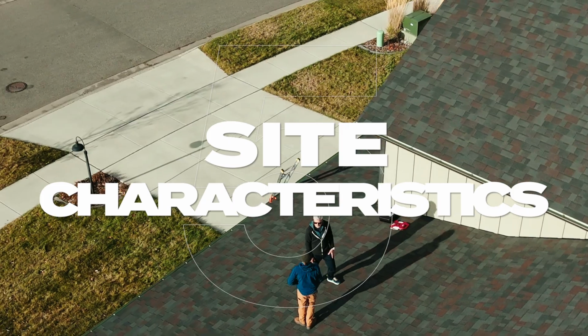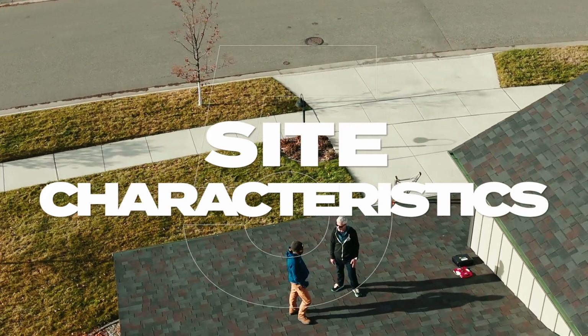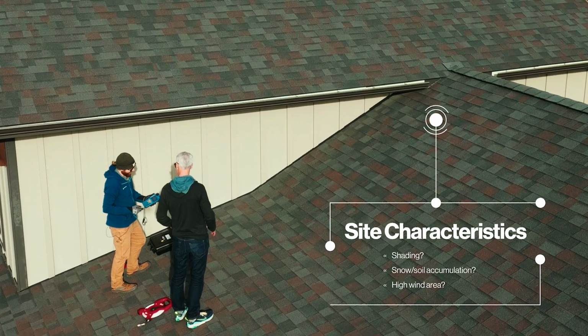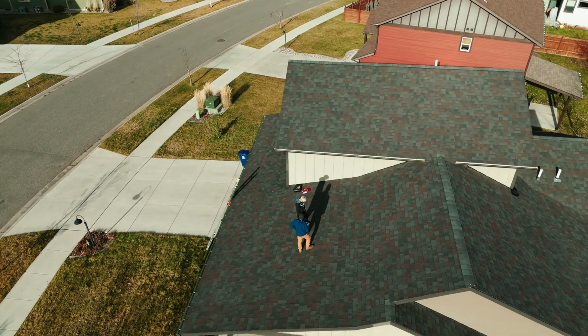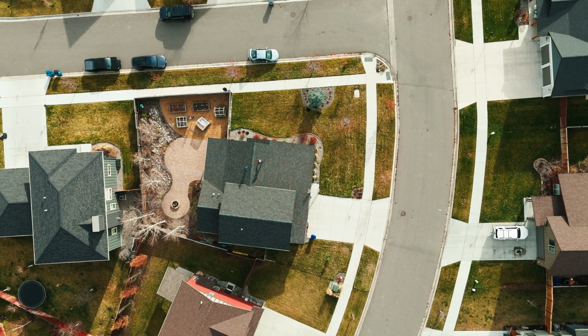Site characteristics are the final step in assessing a home for PV. We're mostly looking for trees and other structures that may shade our array. This is a shade analysis tool. This will give us an idea of any potential shading. Like a solar pathfinder, there's almost nothing that could shade here. Exactly. He has a good solar window.